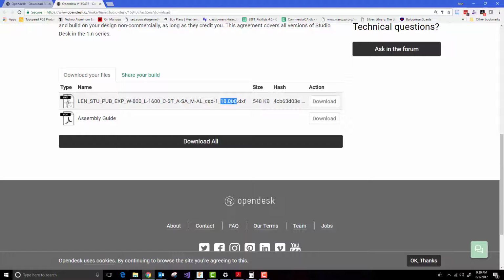everything to stick together. Obviously, if you did say 3/4, I think it's slightly less than 18 millimeter, and so things might be loose. And if you really wanted to go 3/4 and use their designs, you would probably need to go through and look at all of the mortises and tweak their sizes and any tenons and tweak those sizes to fit a 3/4 inch piece of plywood. But you want to know that because there are designs that use 12 millimeter, there are designs that use 24 millimeter.